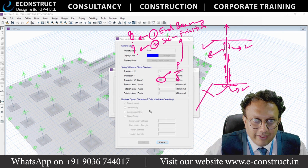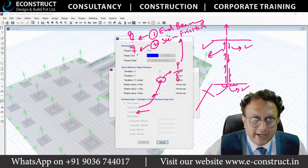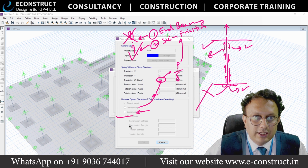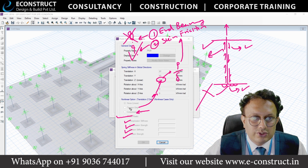So if you are having the compression only option, this is okay. The only moment when it goes to tension, what you will do is in this component you will deduct the end bearing and you will put only the skin friction. And in that context you can go for the elastoplastic also. Elastoplastic means you will give the elastic stiffness, compression strength and all these parameters. But generally this is a little bit complex as a matrix. So what we do is we give the compression only and tension only. Different options we'll give and we'll take the results.